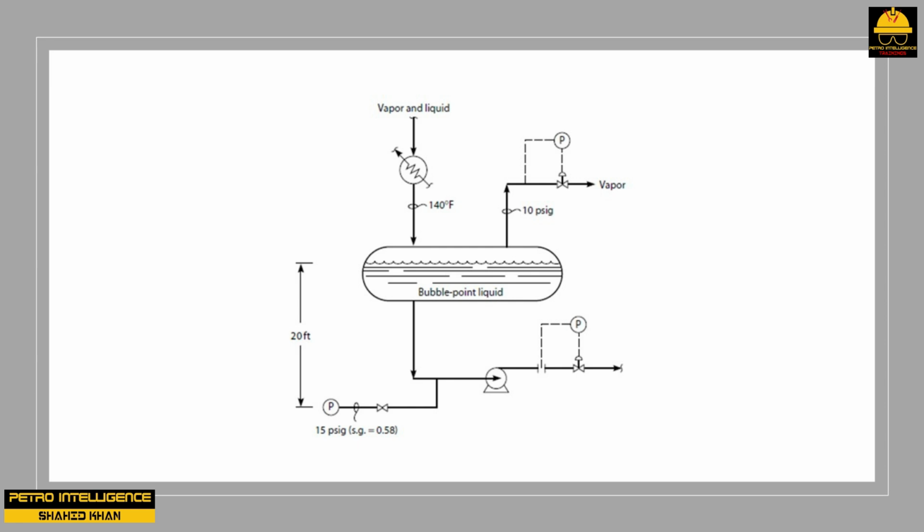Note that the pump suction pressure is the pressure downstream of the pump suction screen, and not a pressure read from a control panel screen. When the required NPSH of a pump equals the NPSH available to the pump, it will cavitate or slip.